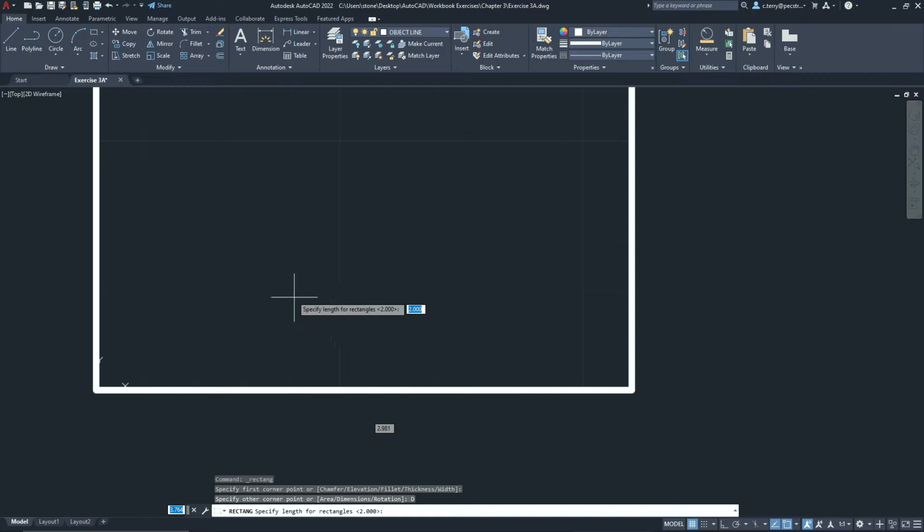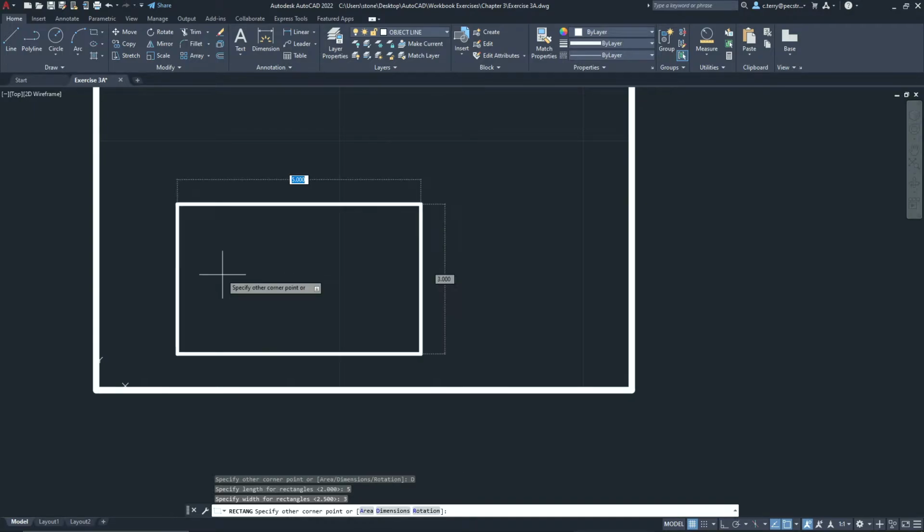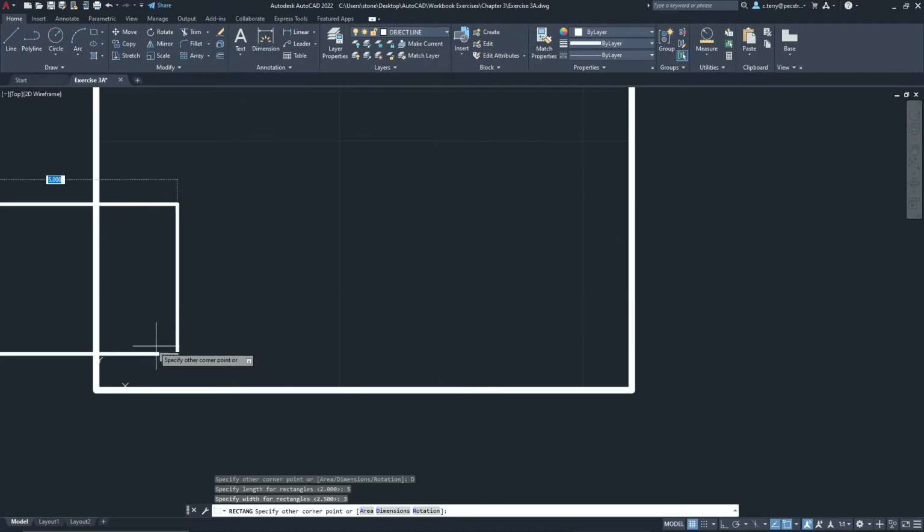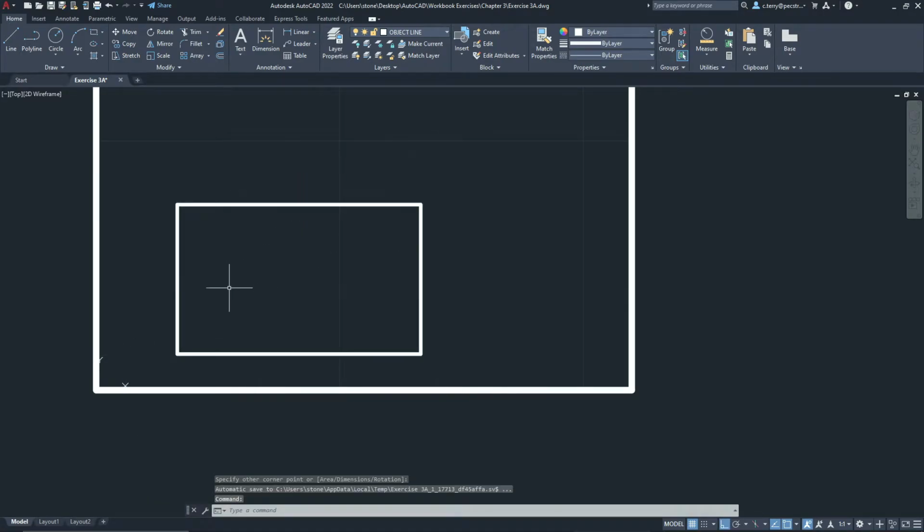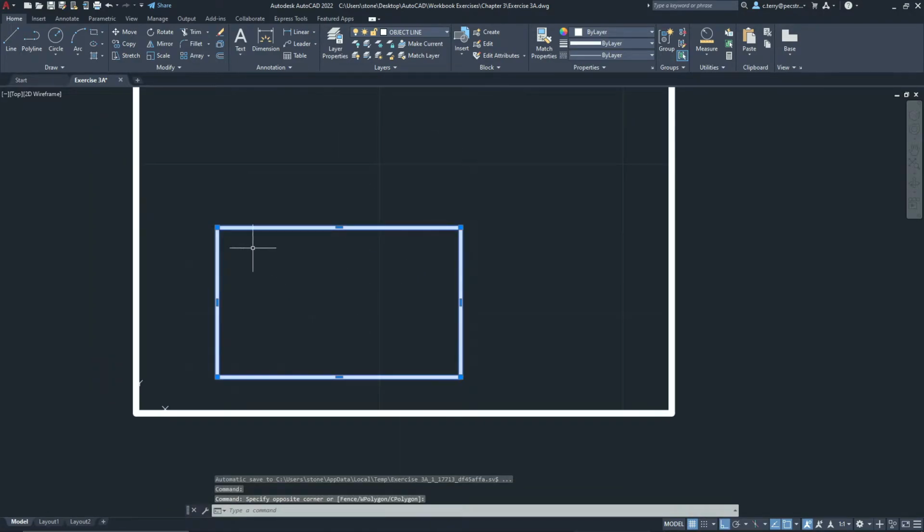So let's click dimensions, and it specifies the length. So let's do a 5, and let's do a 3. Whoop, not a 33, a 3. And now it's specified 5 for the width, 3 for the length, and it's wanting me to put it based on this first point that I selected. So click here. That covers the rectangle, and this is a 5x3 rectangle.